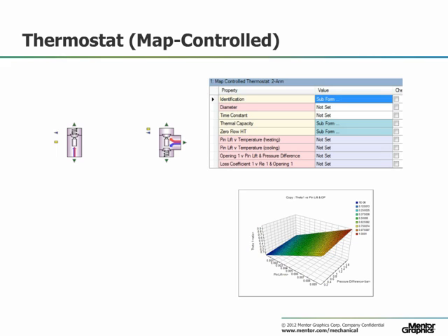An alternative thermostat is available in Flowmaster, which models more detail regarding the thermostat's behavior. In addition to the temperature affecting the valve opening, the pressure difference on either side of the valve will also affect the opening. Additionally, the loss coefficient across the valve will be affected by both the valve's position as well as the flow rate through the opening. If this data is not available, it's recommended to use the basic thermostat as previously mentioned. The inputs for that component are more simplified.